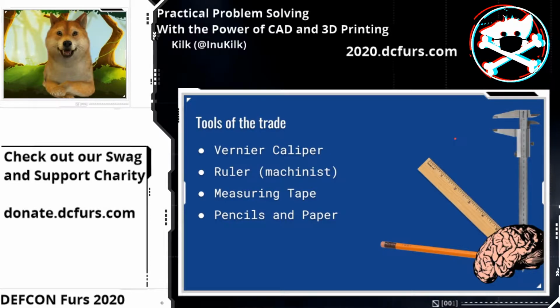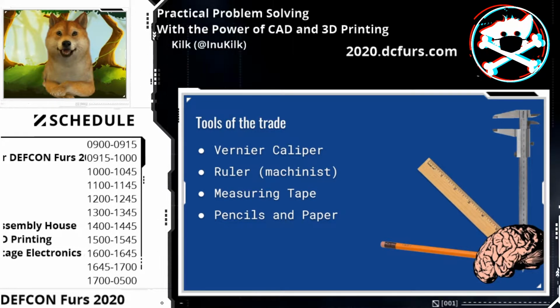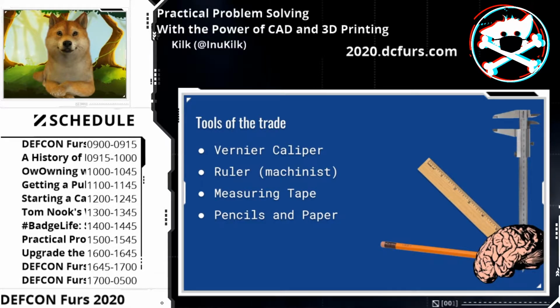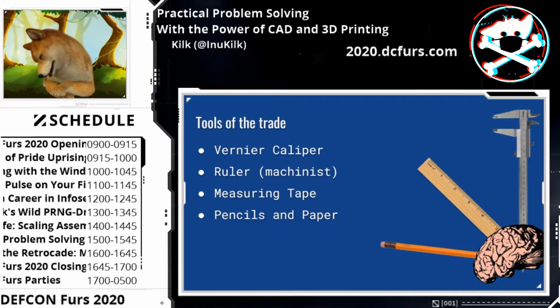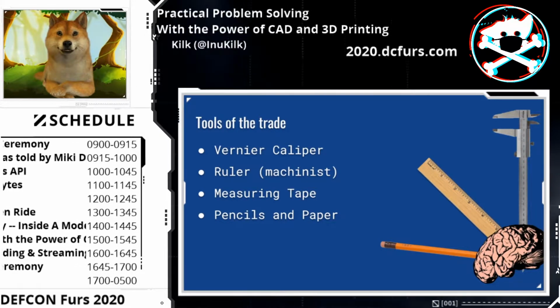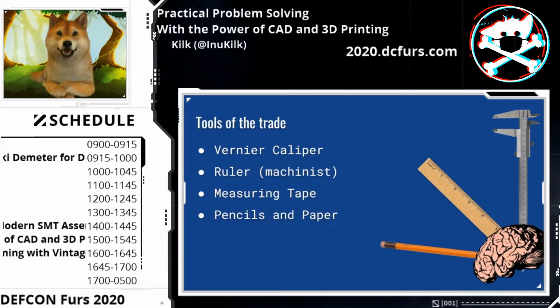So, some tools of the trade. Some tools of the trade that are used often when designing in an engineering environment include a vernier caliper, ruler, preferably a machinist's ruler, measuring tape, and pencils and paper. Vernier caliper is one of the most frequently used tools in the engineering field. It can help get a lot of specific measurements when designing around an object. A ruler is your true friend when you're measuring the length and width. It is vital that you know how to read and use a ruler. There have been many cases where I've been out in the field and there's people that don't know how to use a ruler.